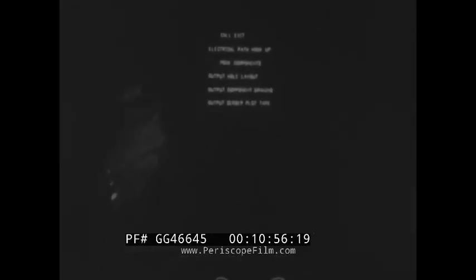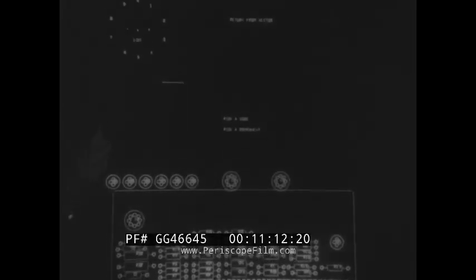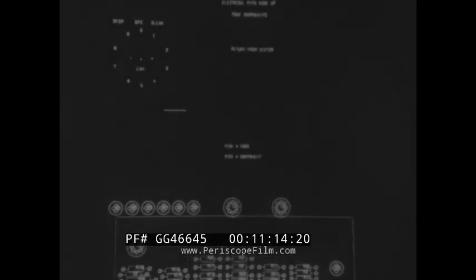Presently, the program consists of two parts: manipulation of components and making the electrical path hookups. The output options will include the automated hole layout patterns, drill tapes, and assembly drawings. In the first section, the operator is given the option to select node values or actual components. By selecting Pick a Node, the computer responds by displaying a numeric font.